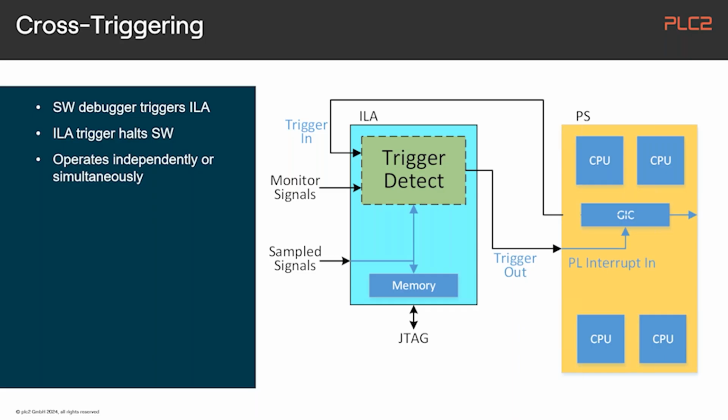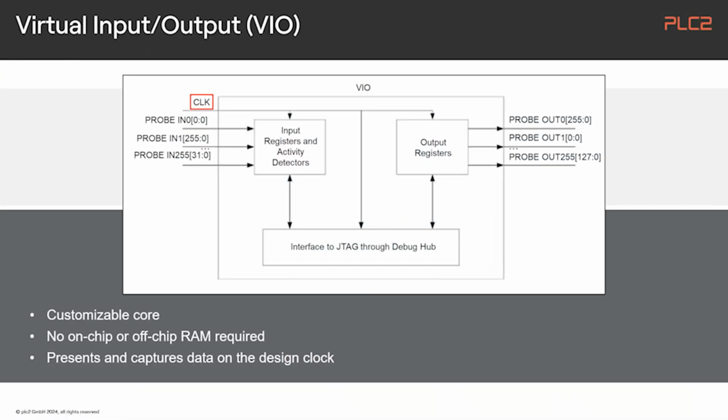And as far as we have a soft implementation of a CPU, we will have then also a soft debug unit, the MDM component, which also can be configured for trigger dependency to the processing system, which is typically here a MicroBlaze soft IP.